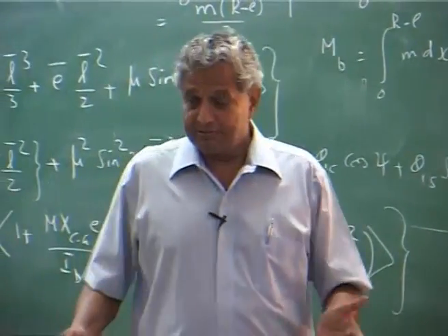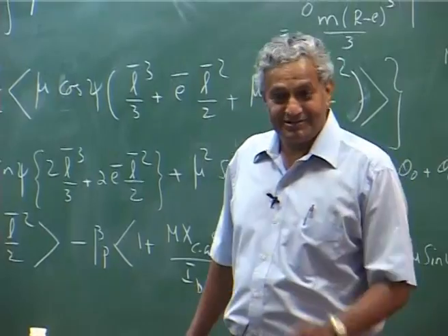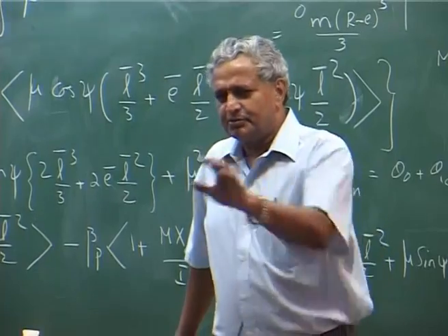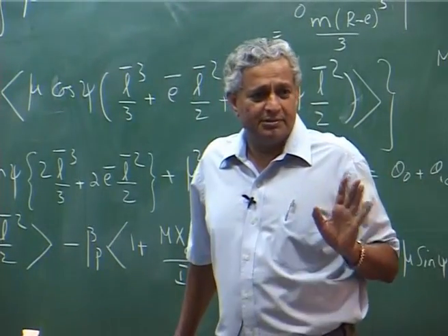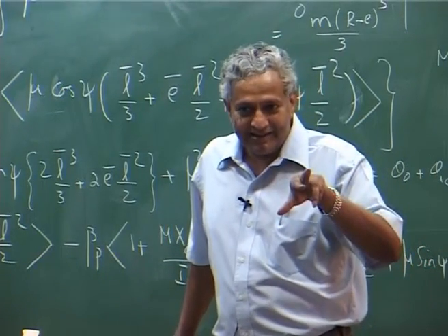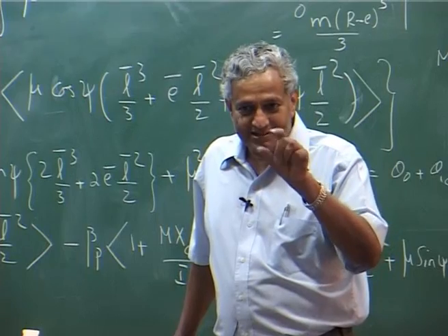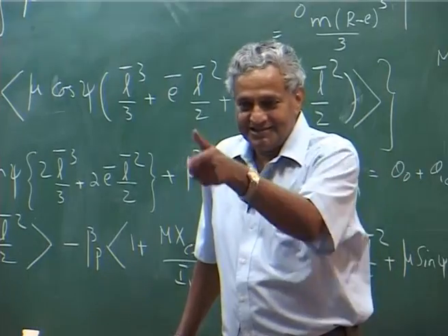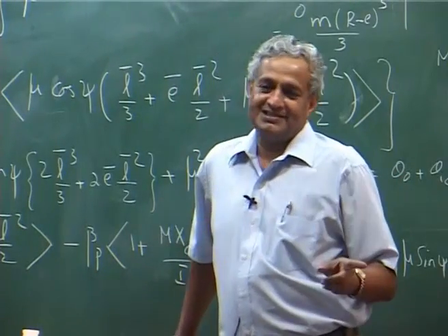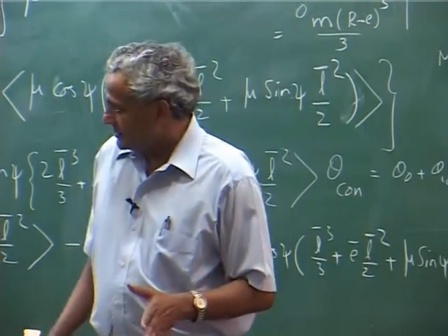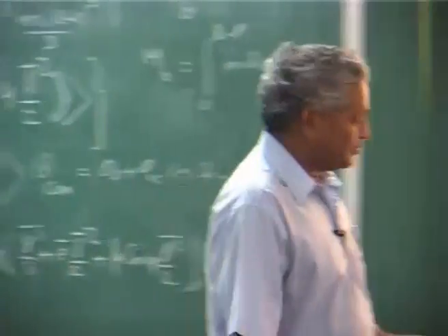Maybe when we solve the full problem, hopefully we will be able to answer your question, but today I do not know. But if you consider only the flap equation, you will not see any difference; both are the same. But if you consider flap and lag, then you will start seeing the difference between precone and pre-droop. You will see the difference in the stability results. All right. Now, this much for the frequency.